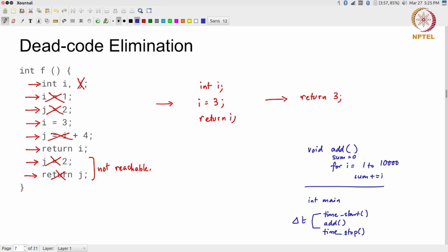And especially while writing hardware or hardware test benches, there could be situations where, if you are not careful, you can end up with a scenario where your entire module has got optimized away because you did not use the outputs that were being generated. Using the outputs basically means some side effect: print out a value, change some global variable, change something which the compiler cannot automatically assume is going to be part of the actual output, and therefore can just be optimized away. So dead code usually doesn't occur by itself, but comes up very often as a side effect of other kinds of changes or tests that you are trying to do.